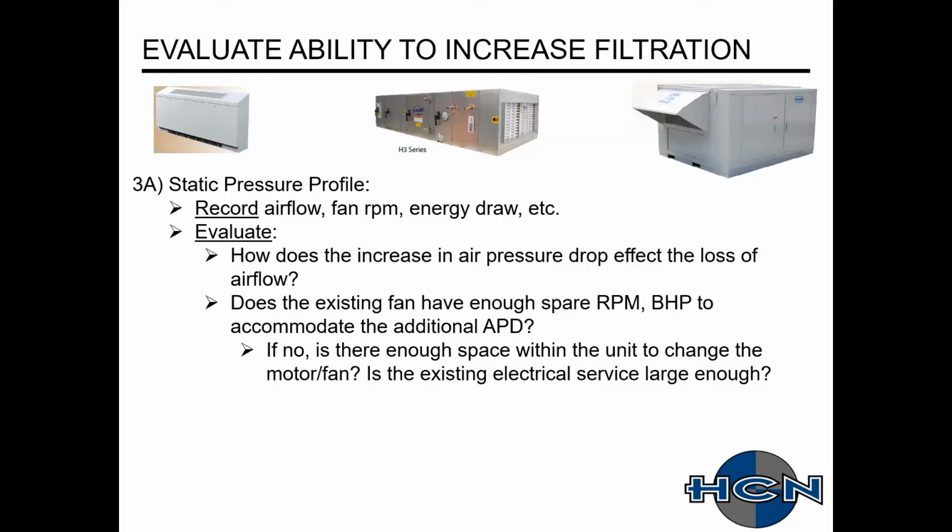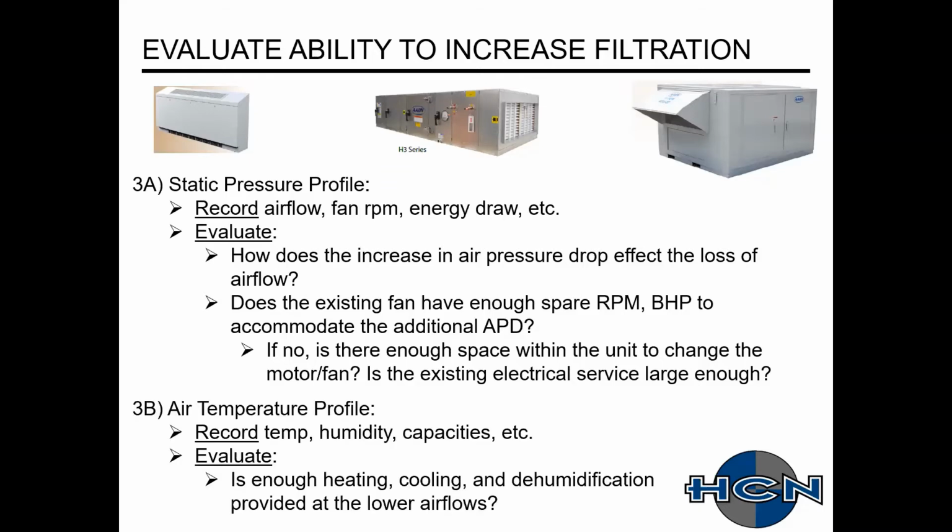And then if there isn't enough fan performance left over, is there enough space within the unit to change the motor/fan assembly? And then the next part is, if you put in a larger motor horsepower, is this going to change your electrical service? Now, part 3B is air temperature profile. As you can see, once again, these would be done in conjunction. The 3A and 3B are related.